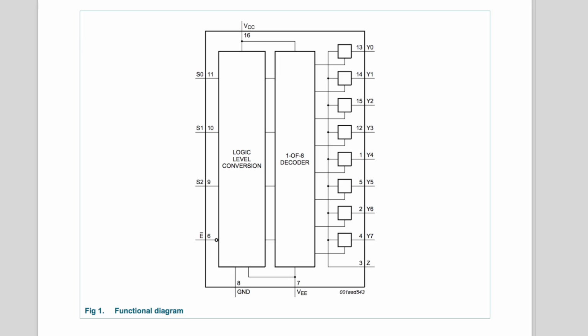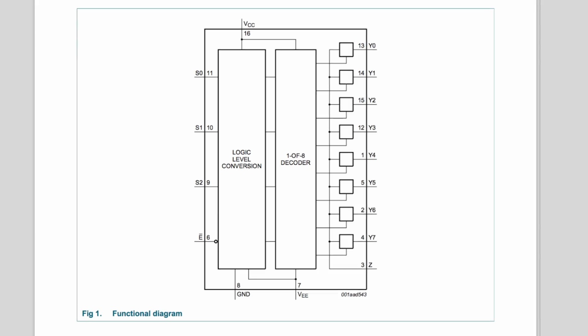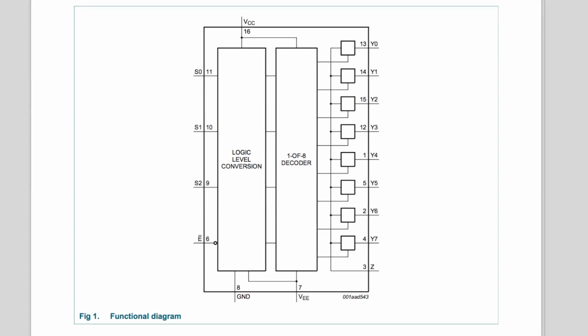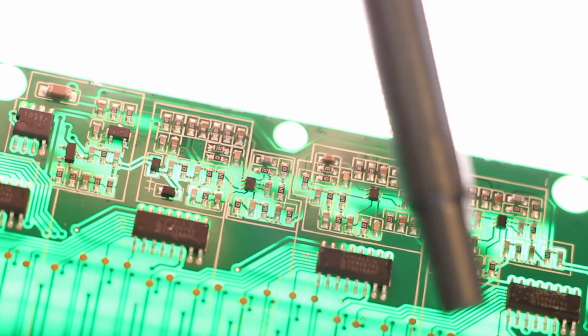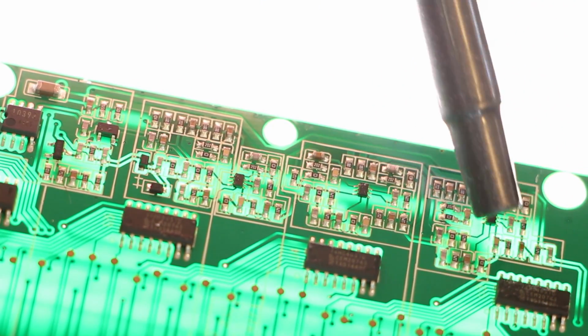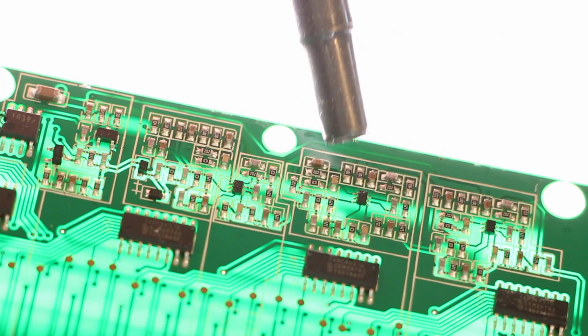Each of these is a 74HC4051, an 8-input analog multiplexer. The microcontroller uses all of these multiplexers to scan through up to 32 inputs one at a time. Through these multiplexers, each input is then in turn connected to a chain of sensitive amplifiers.